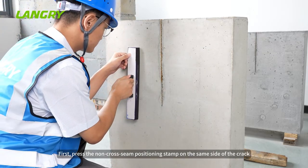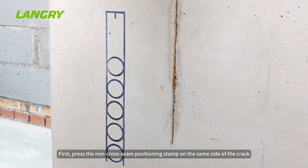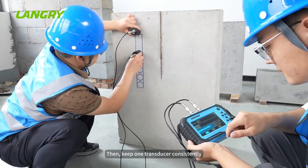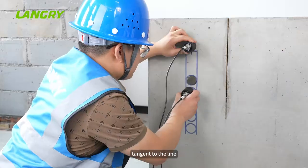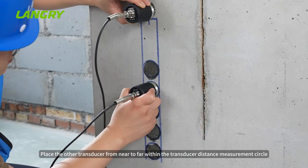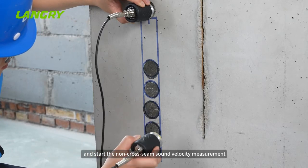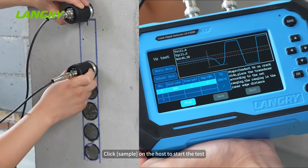First, press the non-cross-seam positioning stamp on the same side of the crack, and apply couplant to both transducers. Then, keep one transducer consistently touching the outer middle of the transducer positioning line, tangent to the line. Place the other transducer from near to far within the transducer distance measurement circle, and start the non-cross-seam sound velocity measurement. Click Sample on the host to start the test.